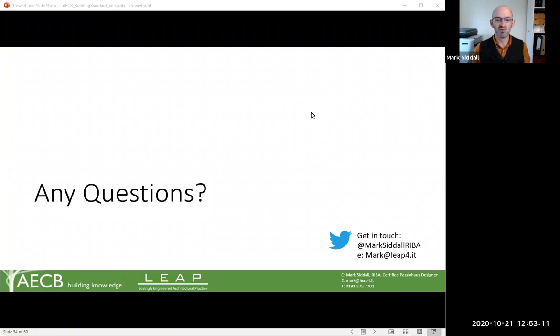It's not that there are more relaxed values necessarily. What we need to be thoughtful of when dealing with a retrofit is appropriate insulation. Are we putting it on the inside or the outside, and how does that have an impact upon moisture? So it's not a case of simply targeting the AECB building standards for retrofit as an energy model. You need to be thinking about moisture issues as well, and that might mean that if you're putting insulation on the inside, the U values that you achieve for the internal insulation are higher, less good, and therefore you need to trade off somewhere else to compensate for those deficiencies.